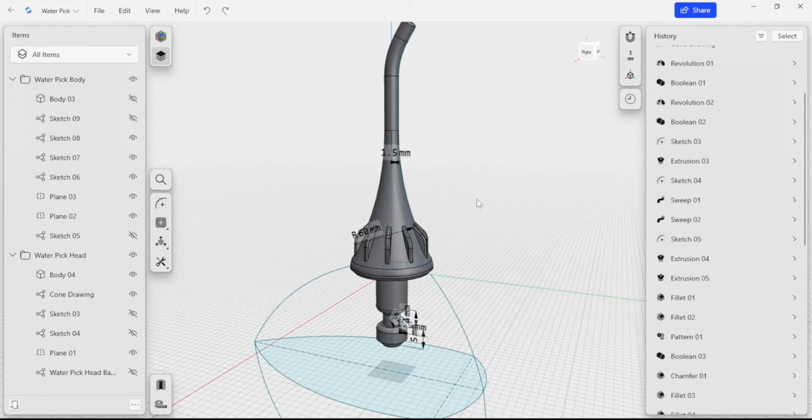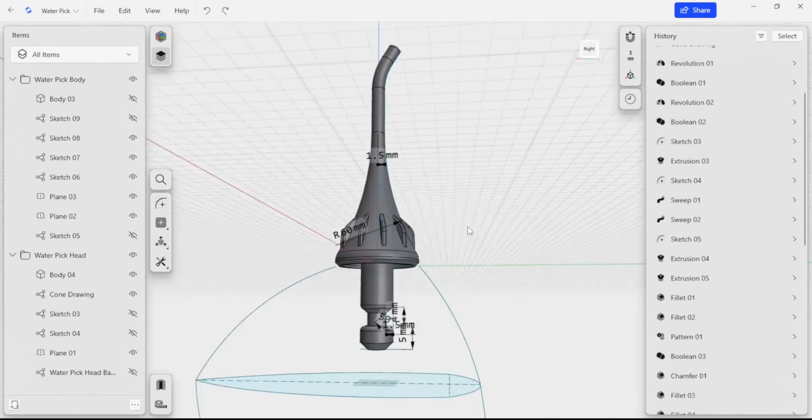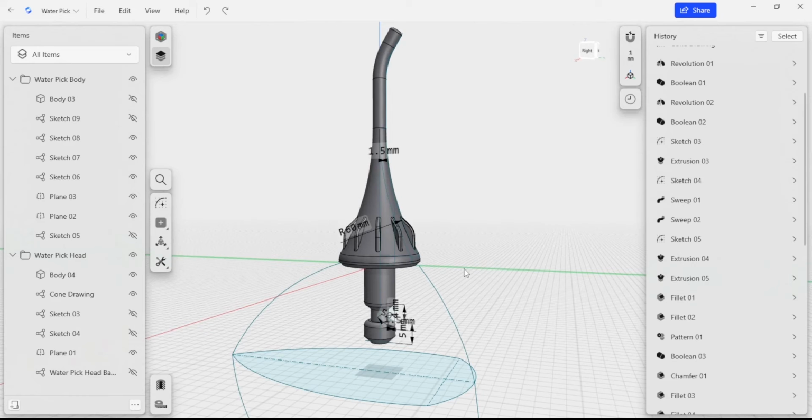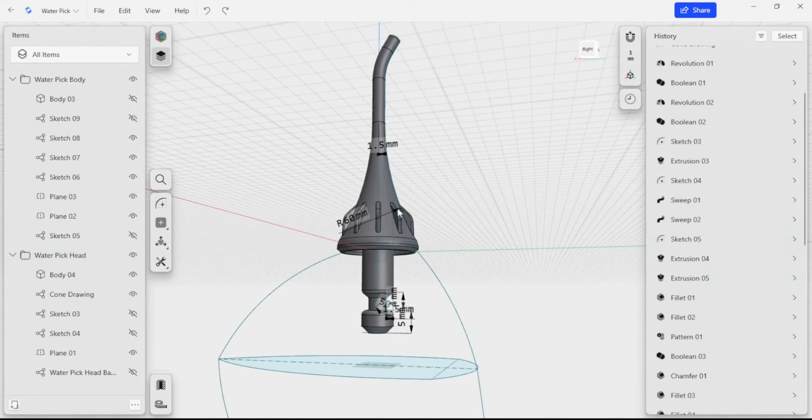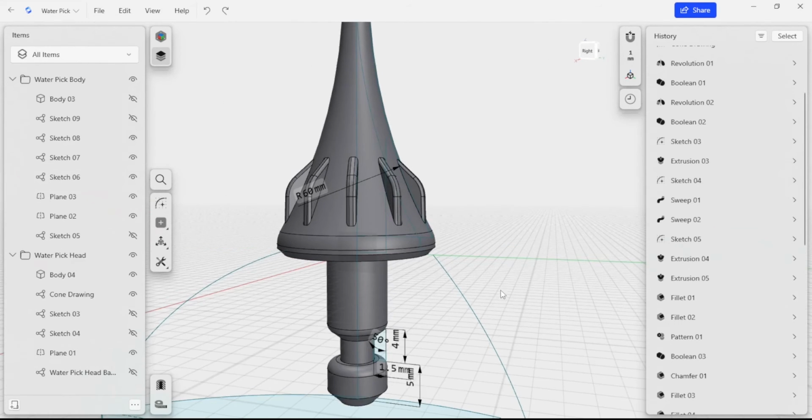One of the big things that I didn't really talk about was doing filleting and chamfering and a lot of those sort of higher level details at the end. Don't do them at the beginning. That way we're not trying to base sketches off of those fine details, which often change around. As soon as those fillets or those chamfers move around, then our sketches tend to break down.